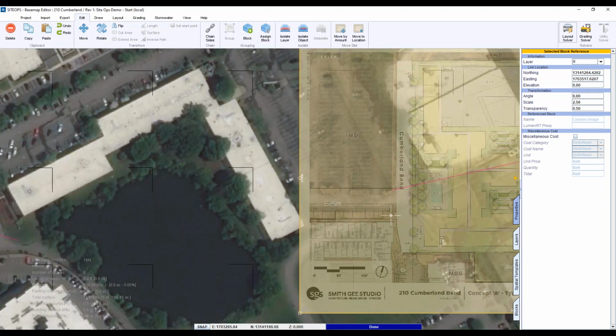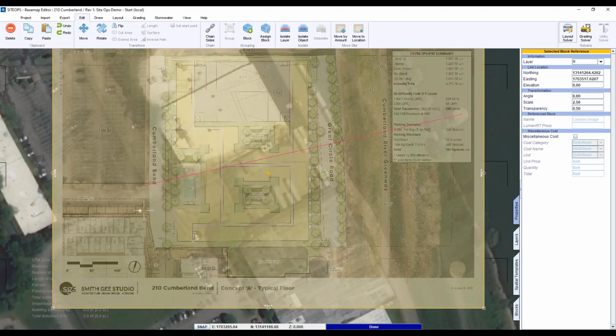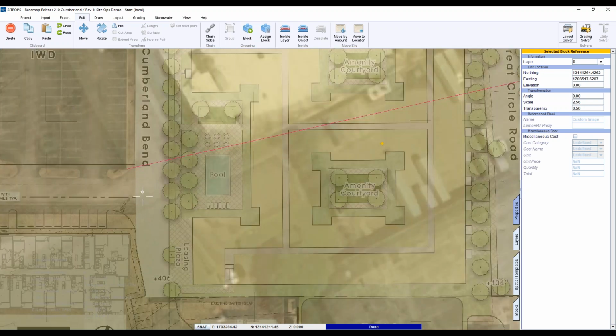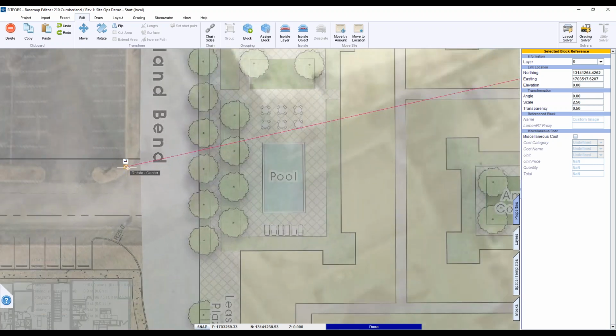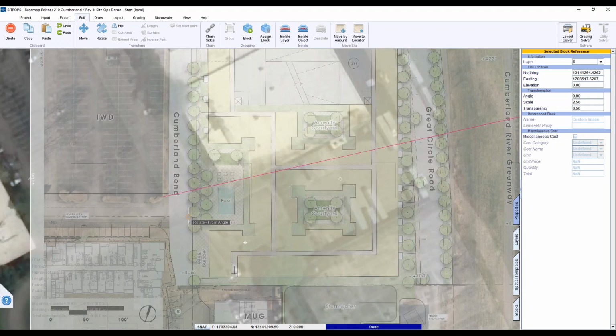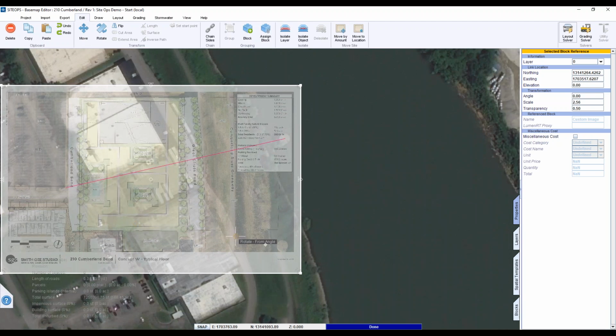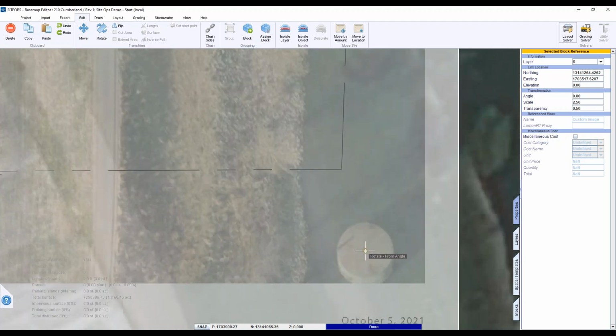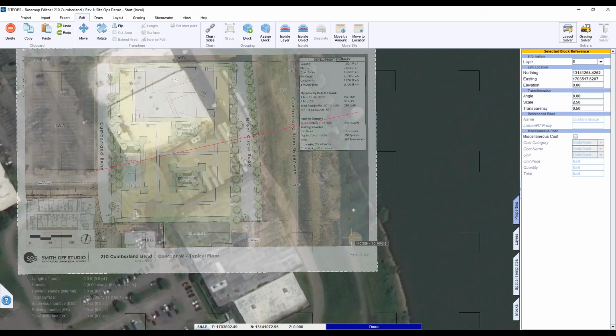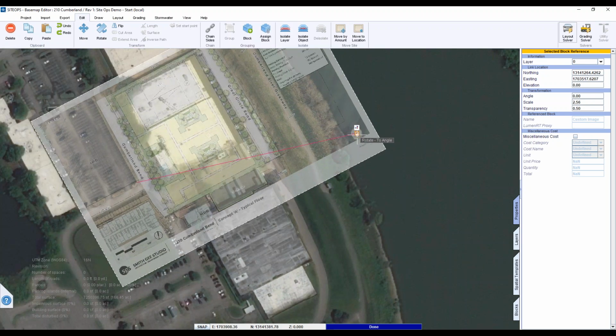So the second step is to get it rotated. So we go with the same item there. Pick this as our point of rotation center. And so for the from angle, we go down to the pylon. Center the pylon. Just rotate it right up until it hits.